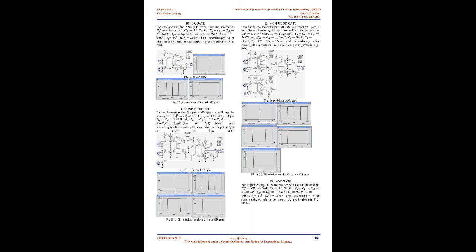Threshold gate-based implementation. The threshold gate-based implementations of the Boolean logic gates have the same basic circuit topology, and we will draw and explain them in the subsequent sections. The threshold gate is built up of a bias capacitance, a tunnel junction capacitance, and an output capacitance. The two input AND and OR gates contain two input capacitors. For both the AND gates, the two input capacitors we are taking are C1P equals C2P equals 0.5, for positively weighted inputs. Whereas, for the NAND and NOR gates, two capacitors hold the values C1N equals C2N